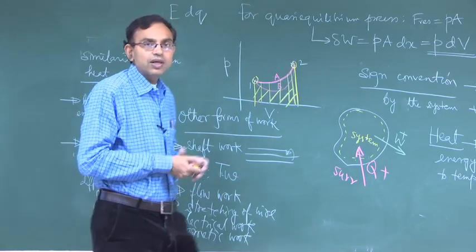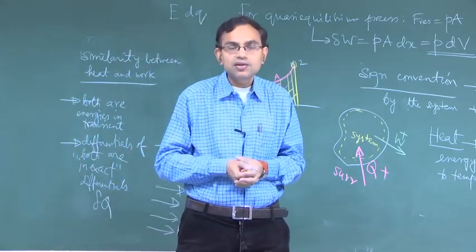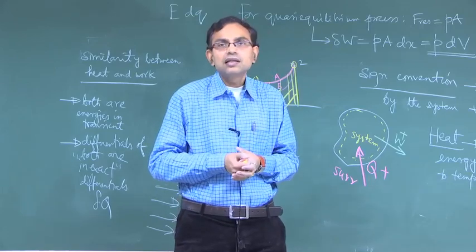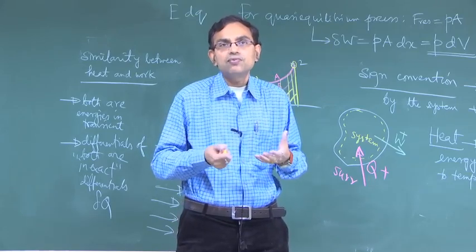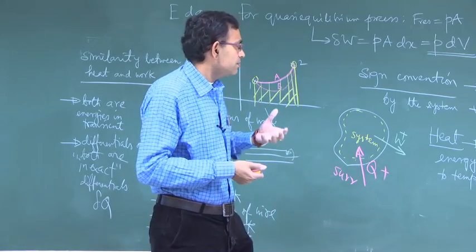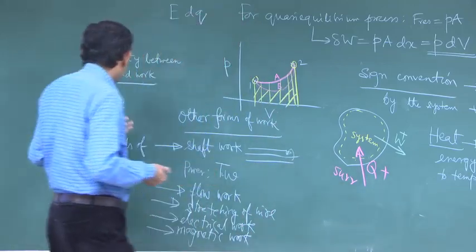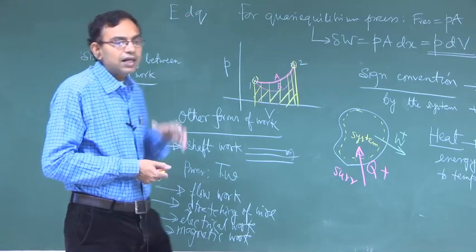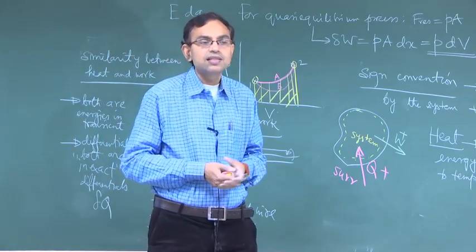So to summarize, today we have understood what heat transfer is, what work done is, and their similarities in terms of notional features like being energies in transit, and their differentials being path dependent or inexact differentials.